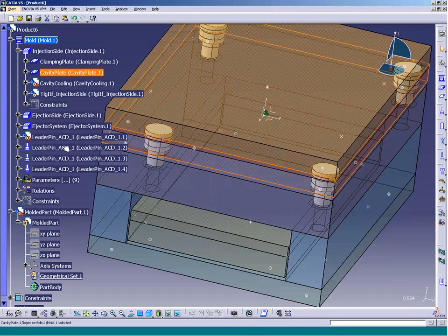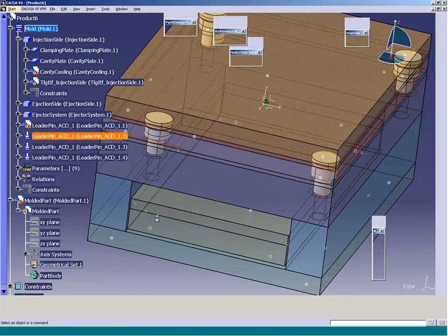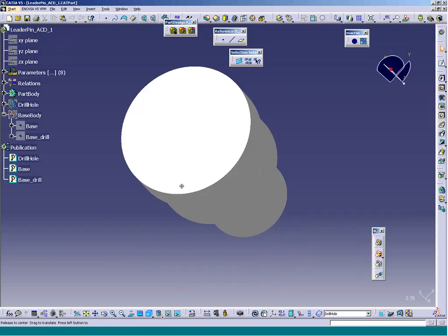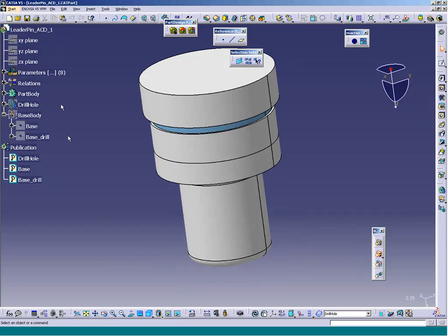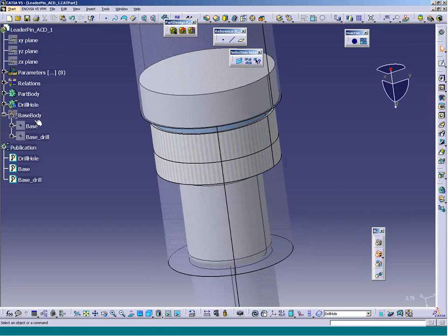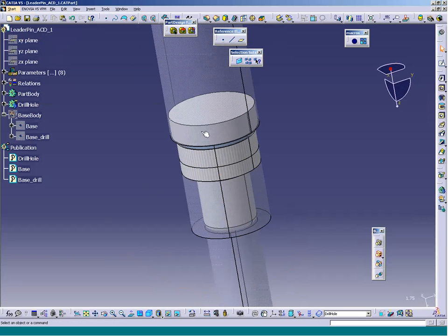these components, these leader pins, have a couple of bodies inside of them. So this is what the leader pin looks like. Everything keeps mobile. And inside of this leader pin, I also have access to another body called drill hole. This drill hole body is the information of the area of clearance that I want. So I can define what level of clearance I want here inside of this. I can actually generate my own drill holes, no problem.